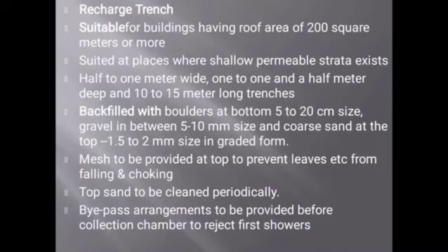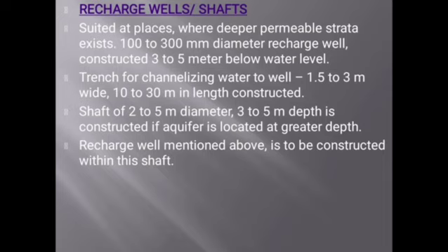Next one, recharge trenches for buildings of up to 200 square meters and more. Permeable strata exist at half to 1 meter wide, 1 to 1.5 meter deep, 10 to 15 meter long trenches. This is what we see in rainwater harvesting in rural areas. This is also what we see in rainwater harvesting in rural areas as a recharge shaft. These are all the rainwater harvesting methods used in rural areas and urban areas. Thank you.